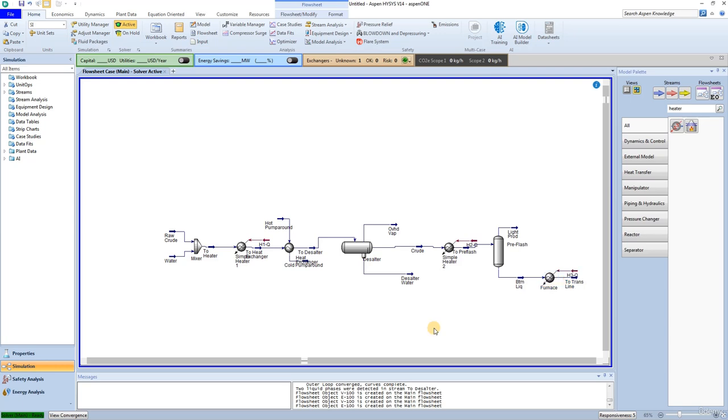Task 2. Add a pipe segment. After the preheated crude exits the furnace, it is ready to move on to the atmospheric crude column. However, we will assume that the atmospheric column is situated about an eighth of a mile from the furnace. To simulate the pressure losses that will occur in the line and check for any other fluid phenomena, the HYSYS pipe segment unit operation can be added.